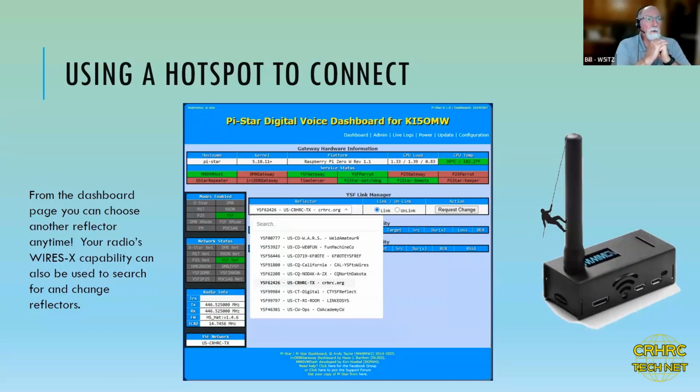And Thomas, maybe I can throw something out that'll help that a little bit. When you think of YSF, Yaesu System Fusion, think of that as the mode that your radio is transmitting from, radio to radio or radio to repeater. Then depending upon how it's going to connect with another system, either another repeater or a system in another part of the world, that's where you get into the difference between a YSF reflector, which is typically an MMDVM solution, or a Yaesu Wires X room. So you've got the Wires X rooms and the reflectors. They'll each have names and DTMF IDs, but they're not cross-system compatible.